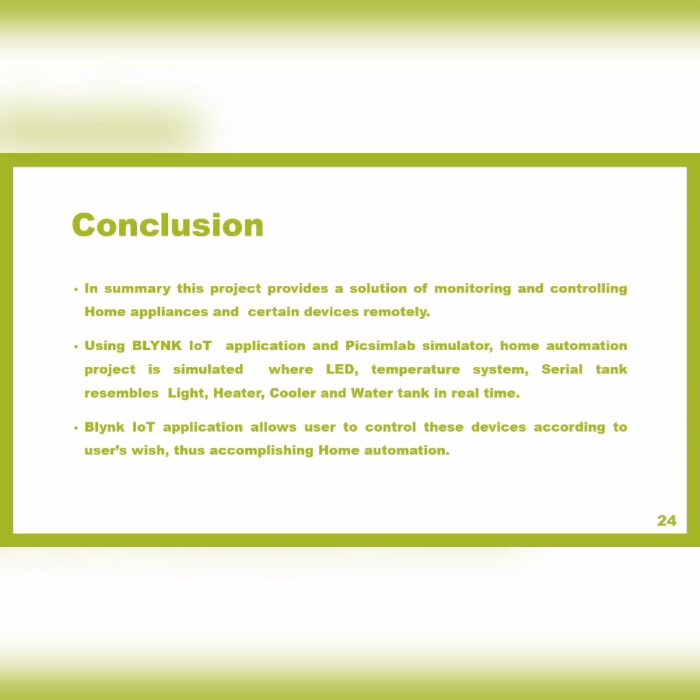What this project does is, we are controlling from a Blynk IoT app on our mobile phones, where when we turn on the heater, it will start and show on the LCD screen. The heater turn off mechanism is controlled by this app. Then the cooler turn on mechanism is controlled by this app, and LED blinking using LDR is controlled by this application.